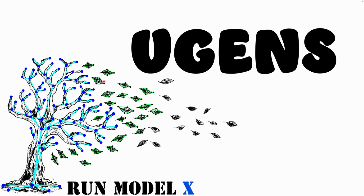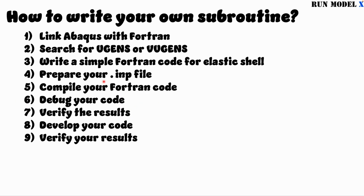In this video I want to talk about the UGENS Fortran subroutine. I want to show you how you can compile a Fortran UGENS subroutine in Abaqus and how you can develop your own subroutine. First of all, you need to make sure that Abaqus is working well with the Fortran compiler, and that both of them are linked together correctly.